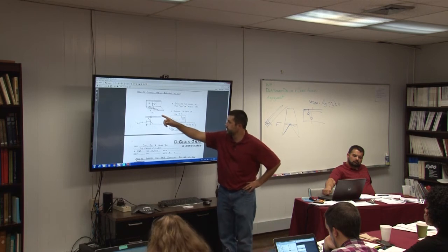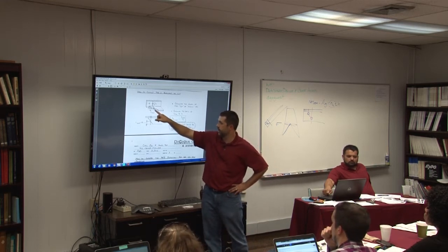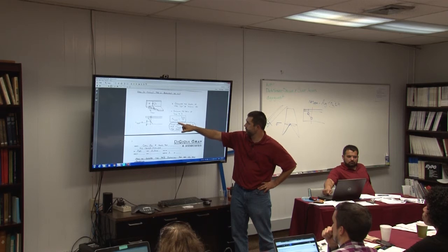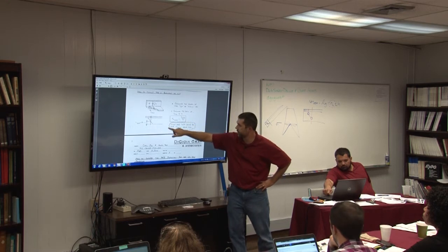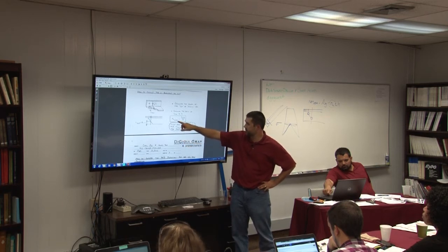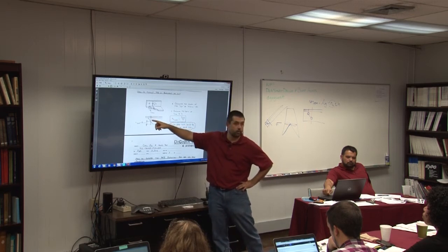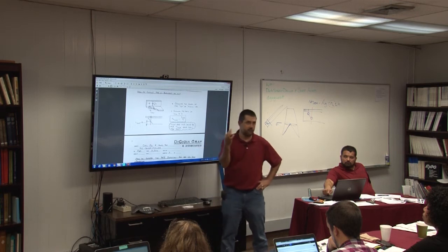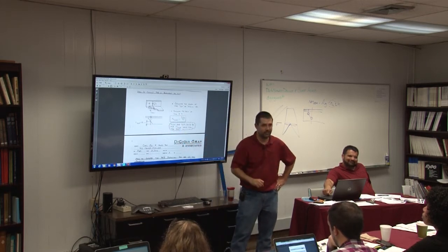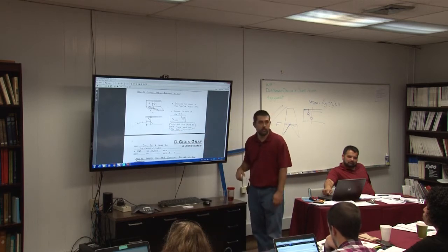Okay, so how do you account for a clip? In this case, I'm actually showing an actual clip as opposed to a block out. If you can calculate or approximate the length of material missing, you take the previous calculation and the number of holes per tower that comes out of that, and then you basically add this value to it. In other words, the number of holes equivalent to this clip is the length of the clip divided by h, which is the diameter of your hole. So if I know that this is 2 inches and I have a 1 inch diameter hole, I'm missing 2 other holes down here. So I can do my previous calculation and then add 2 holes to it. So not tremendously difficult, but again, another step.